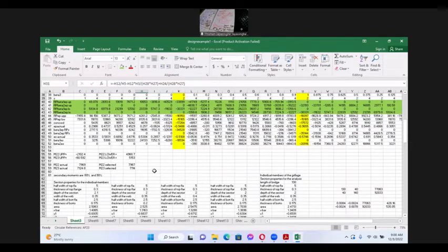So what you have to keep in mind is to find a proper pre-stressing force and ensure that the stress limits are satisfied everywhere will need additional conditions. Those conditions are not as simple as a simply supported case. Simply supported case, the moment you draw the moment diagram, it's done. You can select a P. But in the case of continuous one, you have to do additional calculations to find where it satisfies.